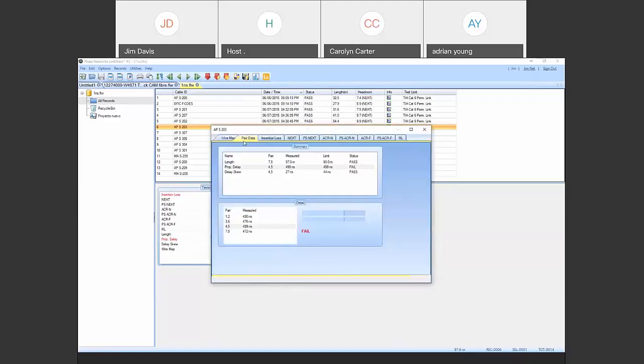we see that the wire map is in good shape. And the length, while 101 meters is a little bit long and 103 meters is long, it's passing because we get an extra 10% there. Now, the problem with this cable is, as Mark was mentioning, that time to get from one end of the cable to the other, the propagation delay, you get 498 nanoseconds to get to the far end. This cable is 499 nanoseconds long. That makes it 1 nanosecond too long. Simple to solve though. All you need to do is push the wall 1 nanosecond closer to the rack.